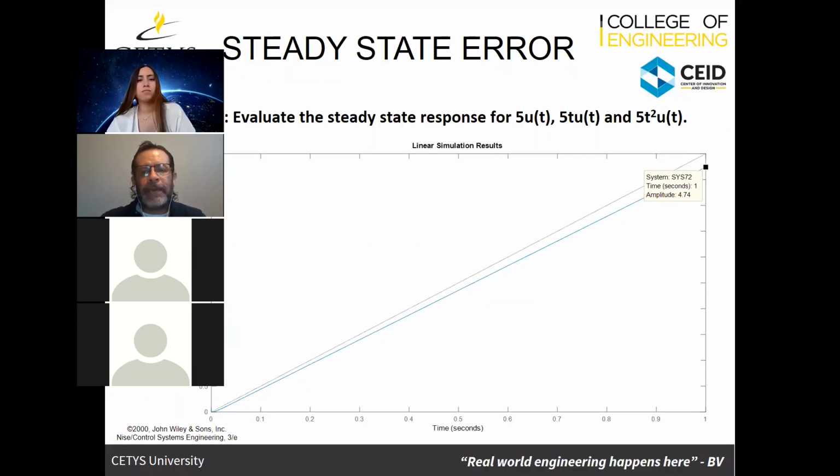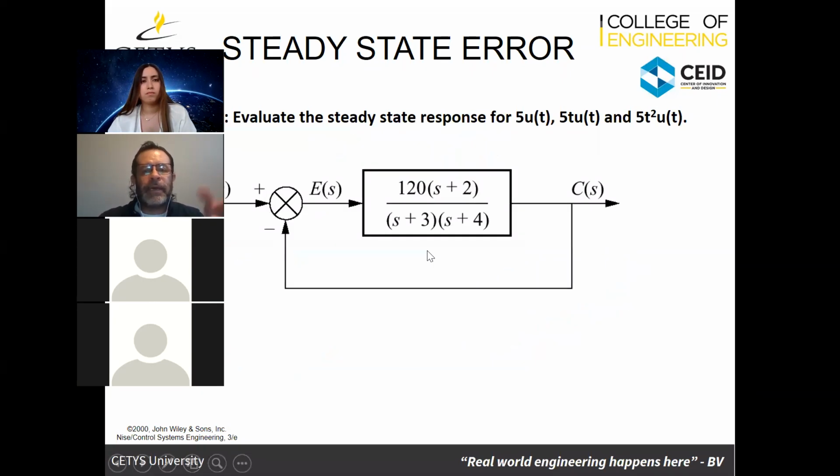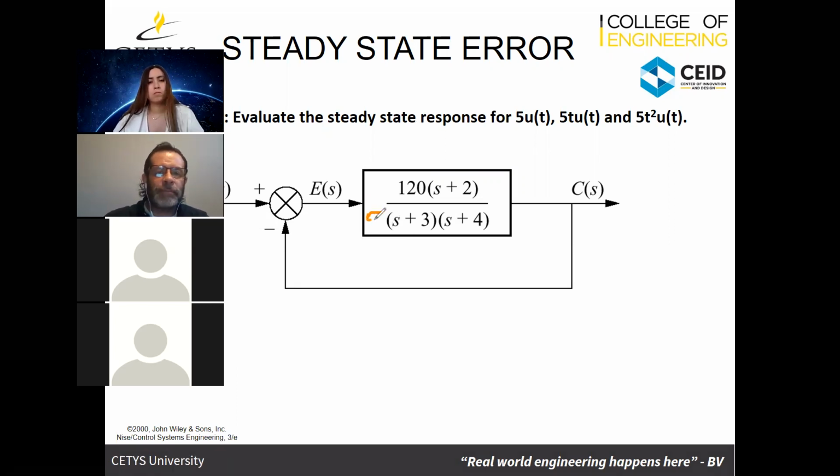And this is actually what we're going to get to, Marian, it's as simple as that. This one doesn't have an S here on the bottom, right? The other one does. If I put an S here on the bottom, somehow in the transfer function, there's a very easy way to do that. If I put an S there on the bottom, the system is going to have 0 steady state error for a step. That means that for a step, it's going to exactly go to the position, and it's going to have a constant error for the velocity, which is the one we just saw.